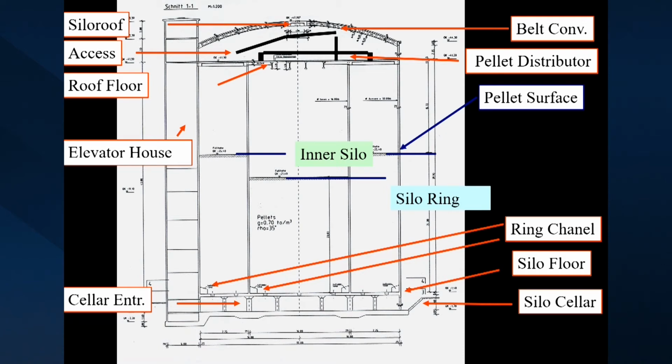If you know how a silo like that has different openings in the bottom, where you empty the mass onto a belt, then you get a so-called funnel flow. That means if you take the mass out here, the material will go down here and you get kind of a funnel, and the material from the top will go into the mass.